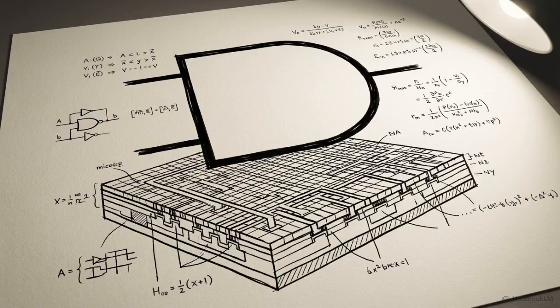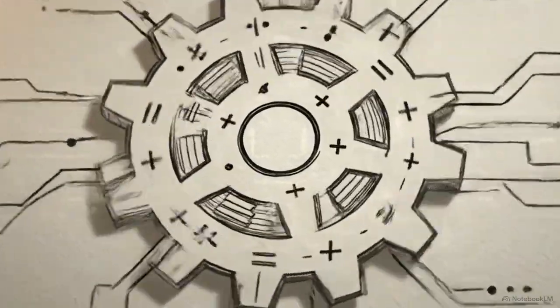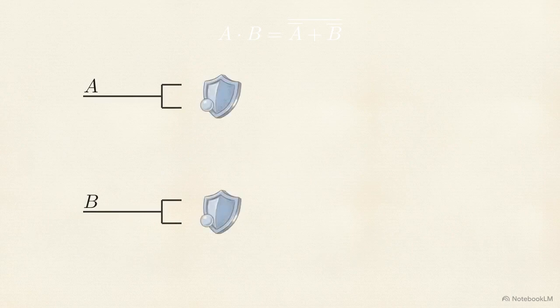With the NOT and OR functions secured, we move to the next required piece, the AND gate. To build this, we rely on De Morgan's laws. These theorems act as engines, letting us mathematically translate operations across different types of logic circuits. The specific theorem we need states that the inversion of a logical OR is mathematically equivalent to the logical AND of inverted inputs. Applying this abstract theorem to physical circuit wiring means we have to isolate variables A and B and invert them independently before they interact.